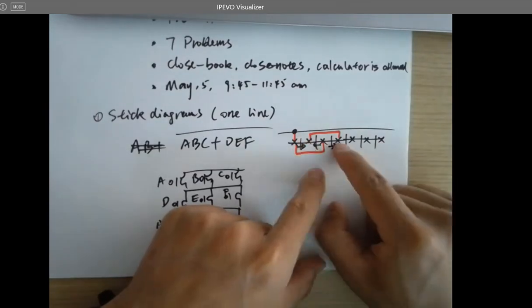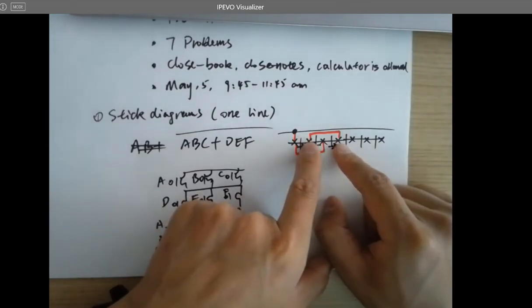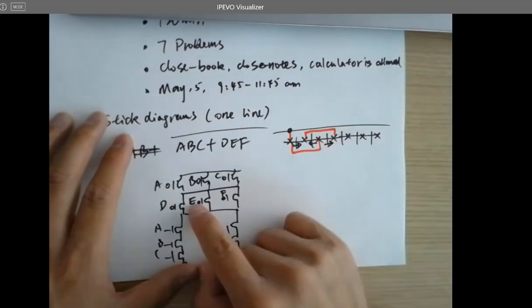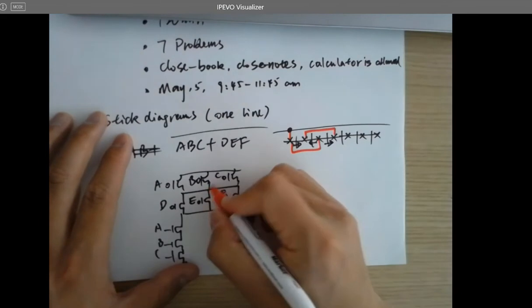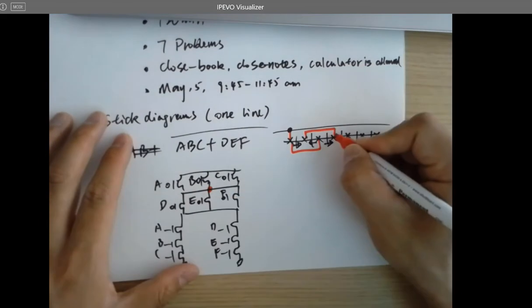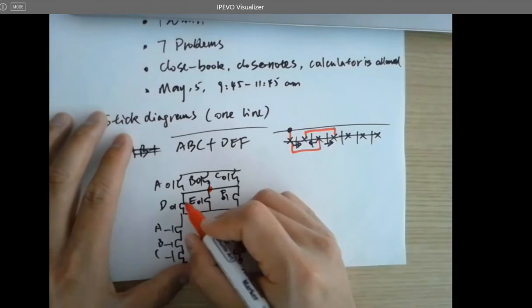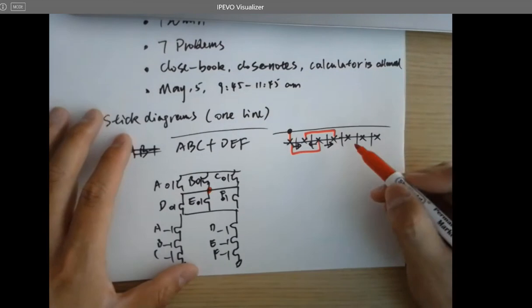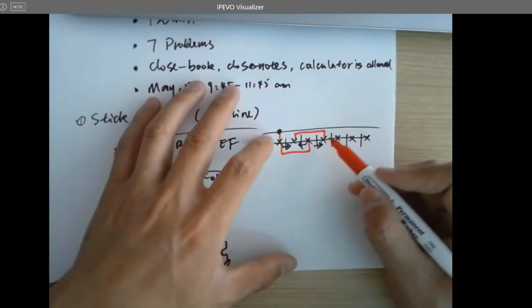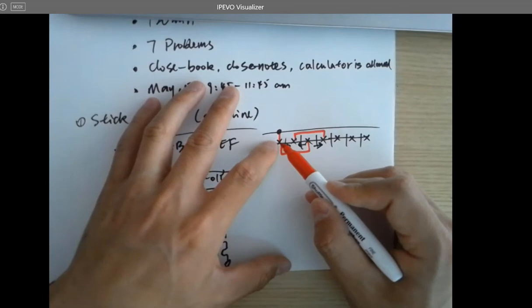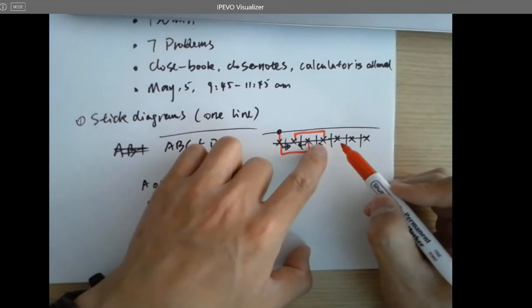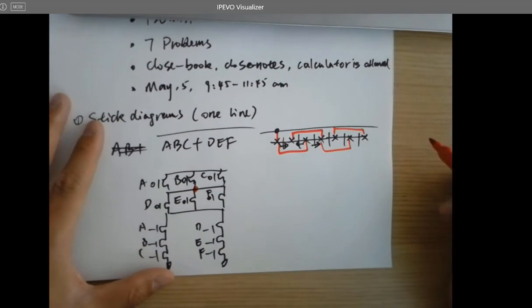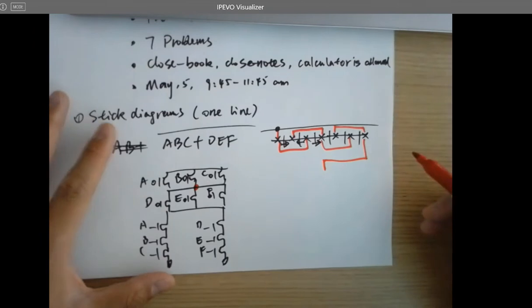So short it, so you can implement it, right? So you can realize that. And that signal will be merged, the final output will be at this point. So this node will be this node. And there will be another 3 transistors in parallel, which is in series with the previous one. So just start it over again, just treat this one as this one, right? So you get a signal starting from here. You just do this. Done. So that's the final output for the PMOSes.